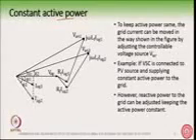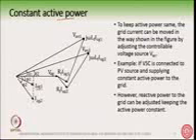So for example, in this diagram, we are keeping the active power constant from the voltage source converter, but the reactive power supplied by the voltage source converter is changing. How can we do that? Here you see that we are drawing two phasor diagrams, one with an IAG1. The grid voltage is VAG, same as before, and then you have RF IAG1, and then you have VAN1.